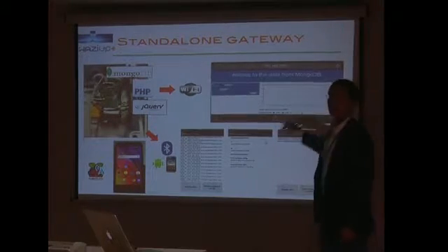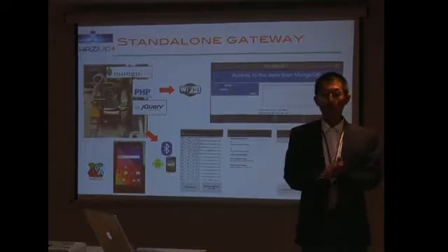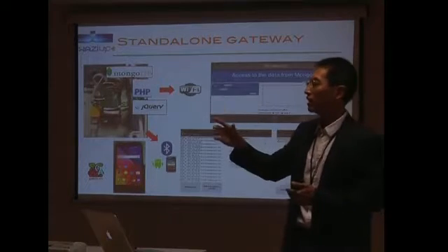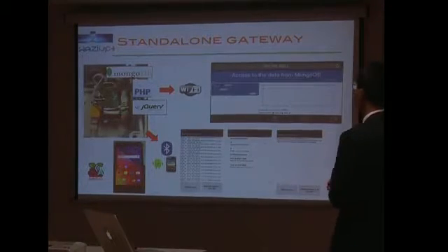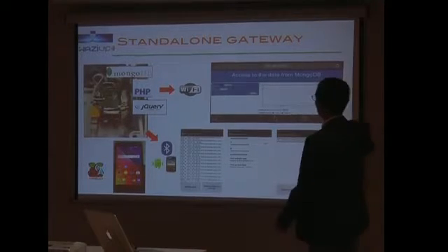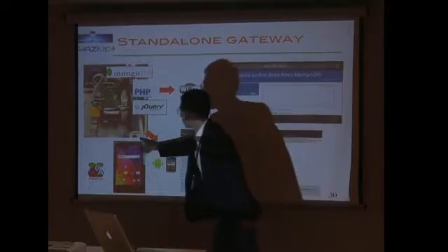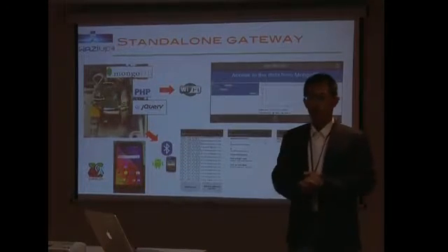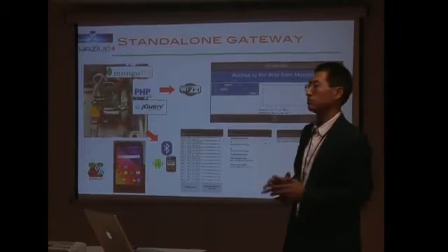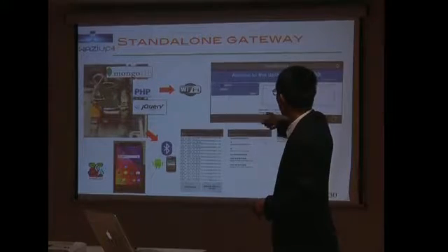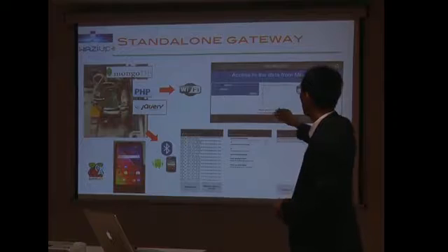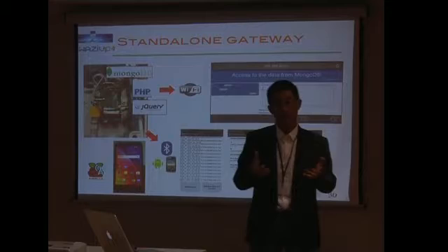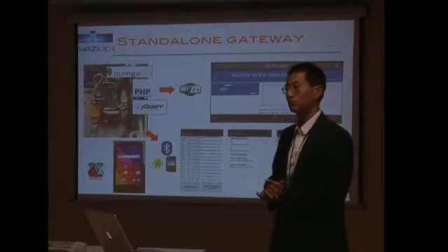All the data that has been received by the gateway, once the internet is up again, the gateway will just push the data to the internet again. So everything is saved on the local database. And also, if you want to interact with, let's say, an Android application, we have a small prototype of an Android application that interacts with Bluetooth, because we also have a Bluetooth dongle here to be able to interact either with Wi-Fi or with Bluetooth with the gateway.